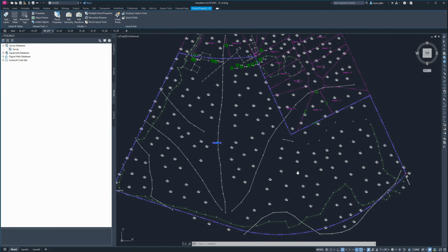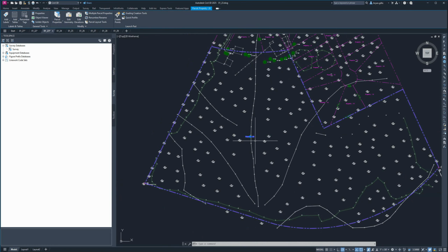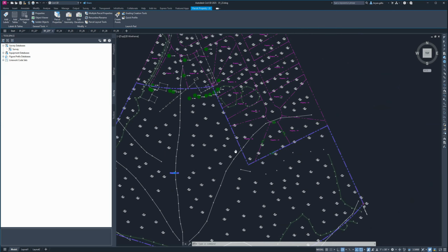That lets you know that there is no hole in this parcel anymore, and the parcel that was created from an object is something that can be more easily deleted, unlike our parcels that are going to be created automatically. This is going to be similar to survey points and COGO points, where while both can be deleted, survey points take a lot more intentional effort in order to remove them from your projects.